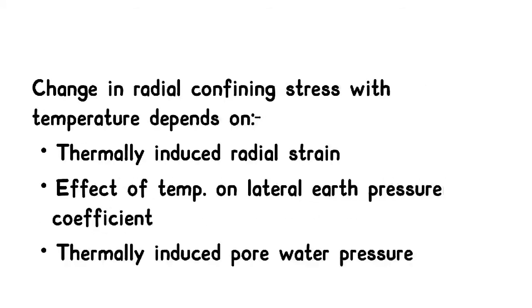Now, there can be a change in the radially confining effective stress, and this change with temperature depends on the thermally induced radial strain plus the effect of temperature on the lateral earth pressure coefficient and the thermally induced pore water pressure.